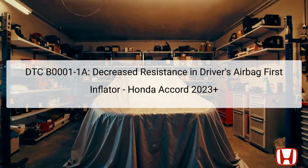The DTC B0001-1A indicates a decreased resistance in the driver's airbag first inflator. This error code is crucial as it directly relates to the vehicle's safety systems, specifically the Supplemental Restraint System, SRS. The SRS is designed to protect occupants in the event of a collision by deploying airbags. A problem with the driver's airbag can prevent the airbag from deploying correctly, putting passengers at risk.